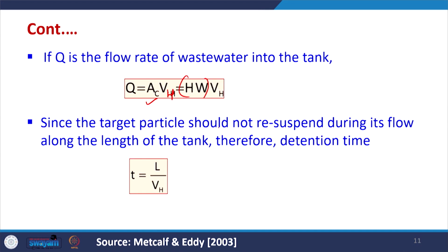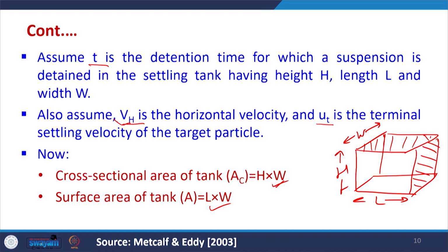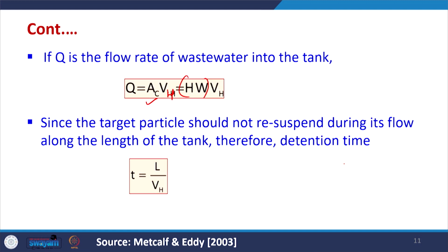Since the target particle should not resuspend during its flow along the length of the tank, the detention time for the target particle is T = L/Vh, where L is the length and Vh is the horizontal velocity. So, this is the detention time.